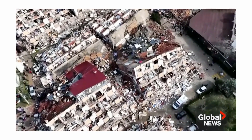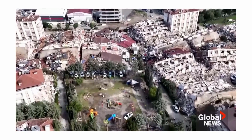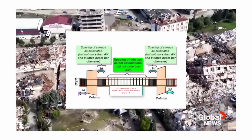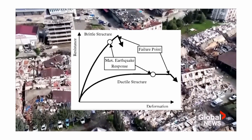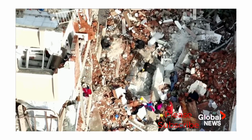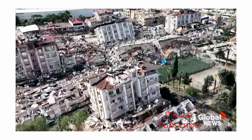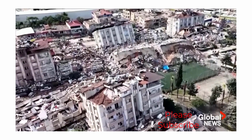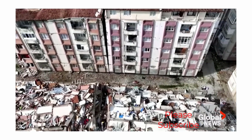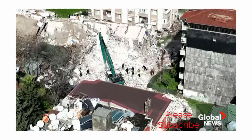But in reality, during the construction and execution phase, enough steel and confining reinforcement to meet the ductility demand were not provided. The basic ductile design philosophy is to survive the main shock and get out of the building safely. However, the collapses indicate that enough reinforcements were not provided as required by the code. So the designer and the constructor should have followed this code very strictly, but unfortunately, these are not followed on the ground. So this also indicates poor construction practice and non-conformity.